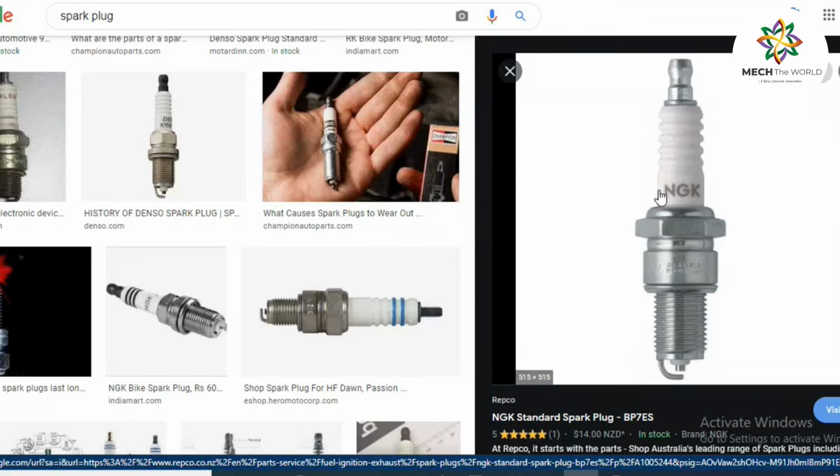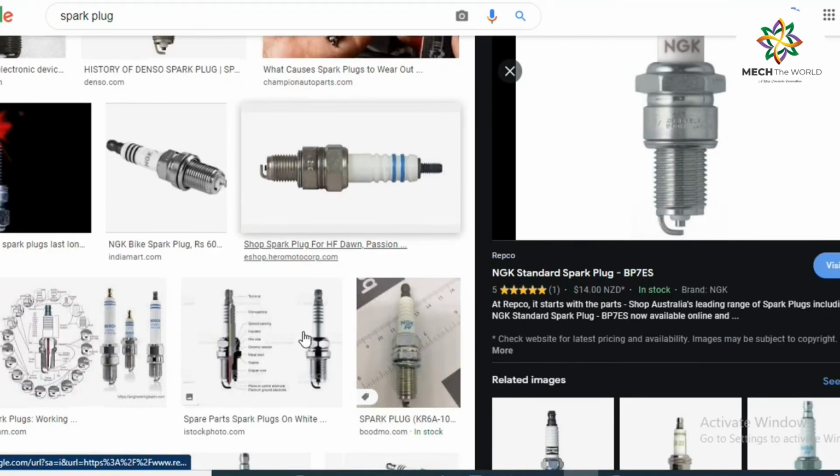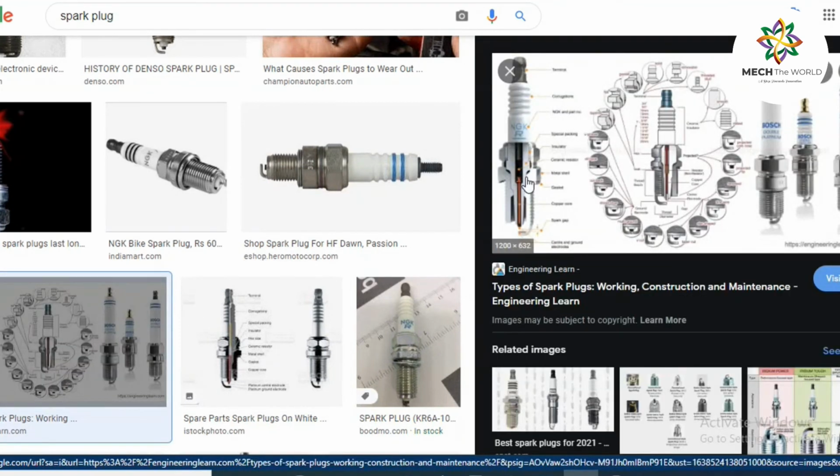If we talk about the motorcycle, then it will give shock to the rider, and if we take the example of a four-wheeler, then it will give shock to the driver. So we want such a material which can resist the high temperature and which should not transmit the electric shock to the car body or two-wheeler body. So ceramic possesses both of these two properties. That is why ceramic is preferred for making spark plugs.